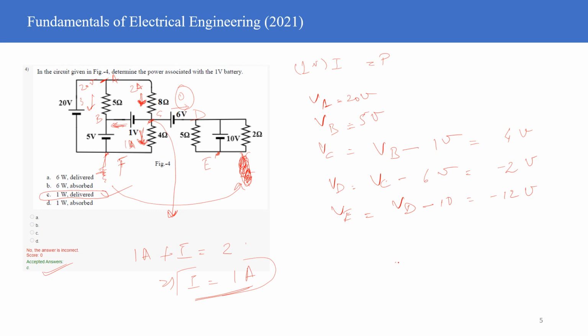Just let me ask you, if I1 plus I2 plus I3 plus so on up to IN, if I add them, the sum will be equal to 0, right? Right, Hassan? Yes, sir. So yes, this is the fundamental law. There cannot be a net current flowing into a single node, right? It has to flow out of it. So if there is no outflowing current, the sum must add up to 0.